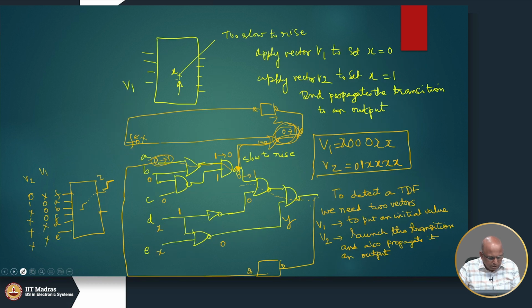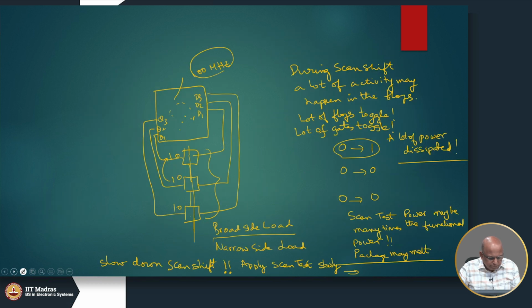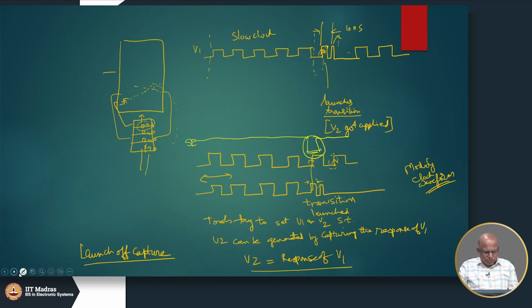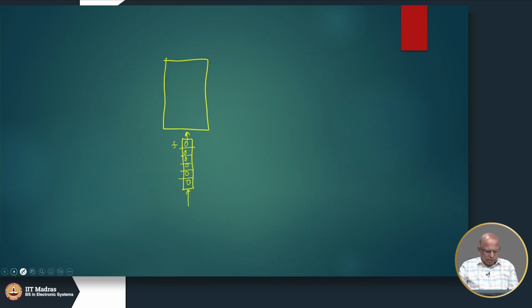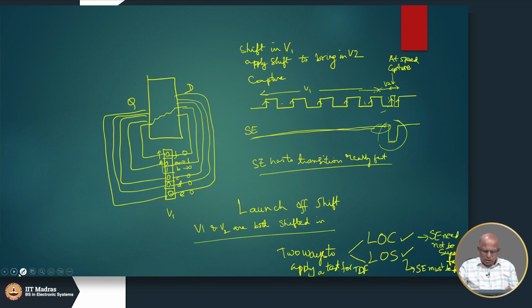So as a result, it's important to do speed testing. And remember, we can also do binning. Okay, we can save some chips from being thrown, right? If it doesn't work at 1 gigahertz, see if it works at 990 megahertz or 980 megahertz, and see if there are some which will work at 1010 megahertz or 1020 megahertz.